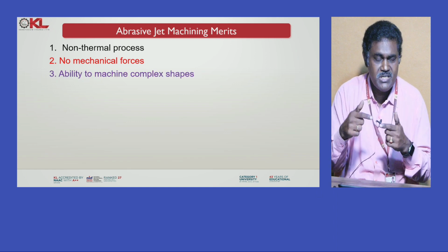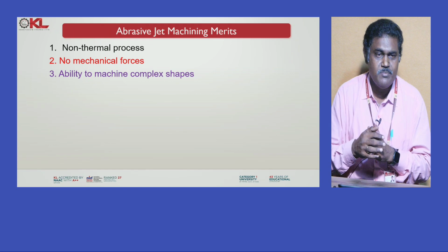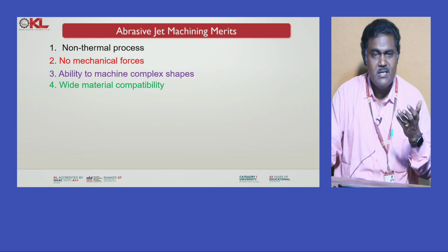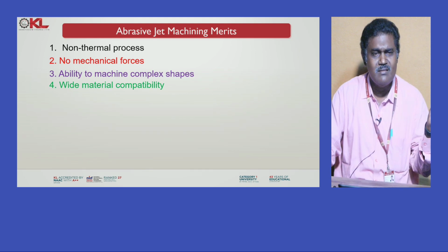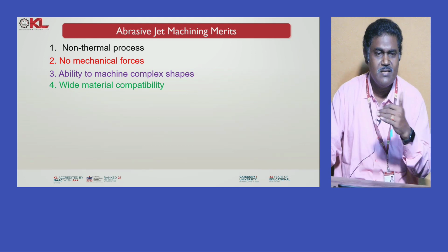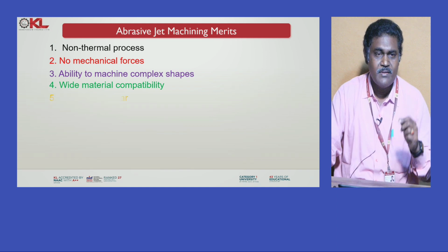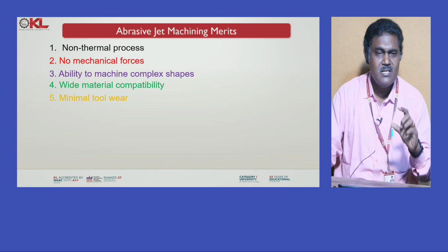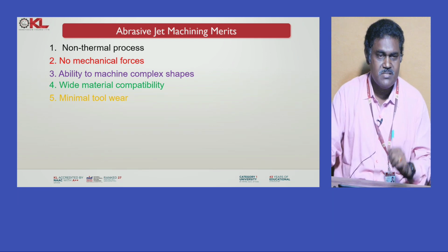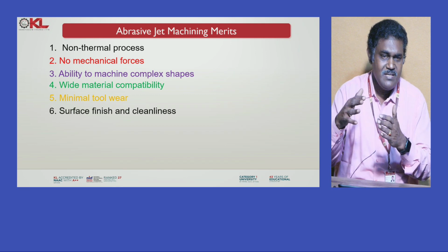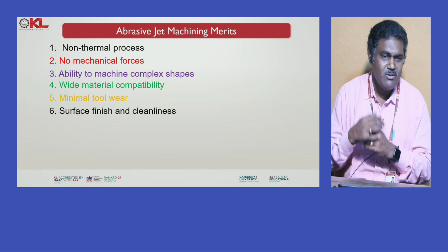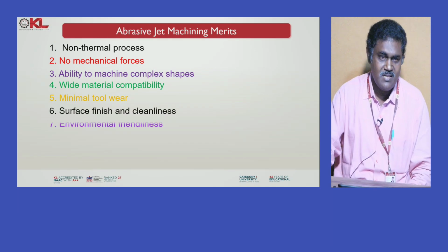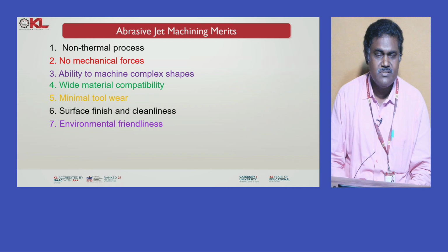And the ability to machine complex shapes of objects. And wide material compatibility: this can be used on a lot of materials, all materials are compatible. Then minimal tool wear. Tool wear is very minimal because there is no direct contact between the tool and workpiece. Surface finish and cleanliness is achieved. You can obtain an acceptable surface finish and cleanliness of the surface. That is one merit of abrasive jet machining.